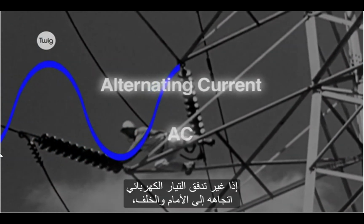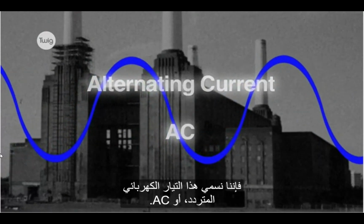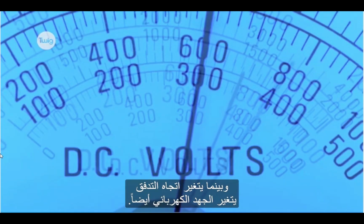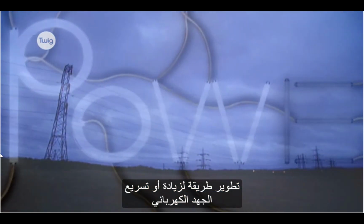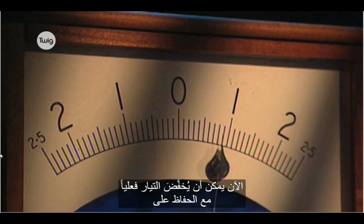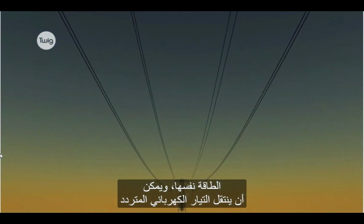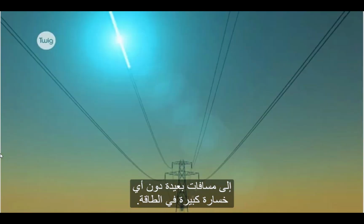If the flow of electricity switches direction back and forth, we call this alternating current, or AC. As it does this, the voltage is changing as well. This unique property of AC has allowed engineers to develop a way of increasing or stepping up the voltage in power lines. Now the current can actually be decreased while maintaining the same power, and so AC electricity can travel long distances without any significant power loss.